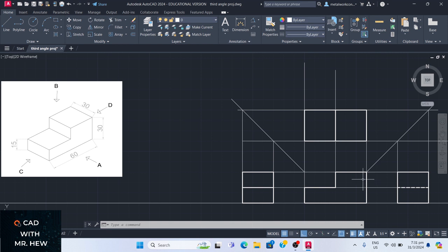Now, what I'm gonna do now, I'm gonna label the drawing, right? So I'm gonna use a text command, so write text. I'm gonna specify the starting position. 4 millimeters is a better height. Rotational angle, enter 0. I'm gonna type with caps lock on.